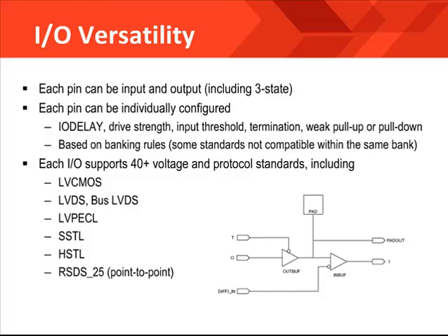The versatile SelectIO resource was first introduced with the Virtex family of FPGAs several years ago. It has been enhanced with every new product family ever since. I/O standards have been added and selected to support what our customers require. Spartan-6 FPGAs support over 40 I/O standards, including those you see listed here. But check the datasheet to see if your I/O standard is supported. That'll have the complete list. Note that there are memory-specific standards of various classes, differential standards that require 2 I/O pins to receive or transmit signals. The differential signaling standards include LVDS, LVPECL. The single-ended I/O standards include LVCMOS, SSTL, and HSTL.